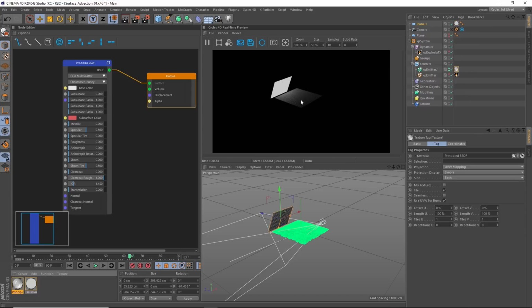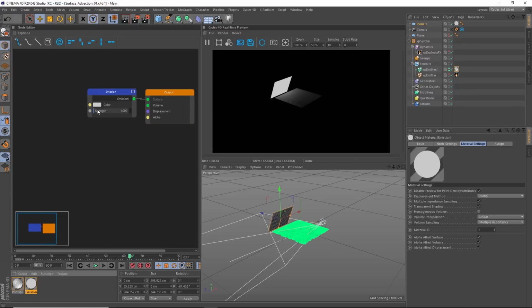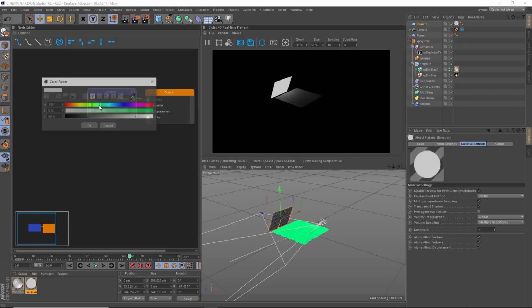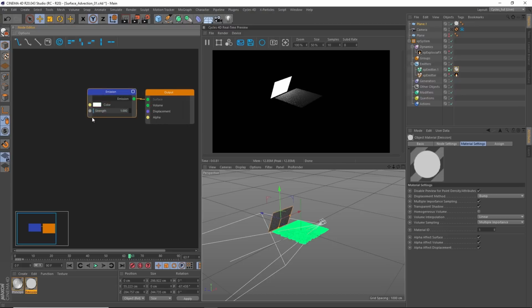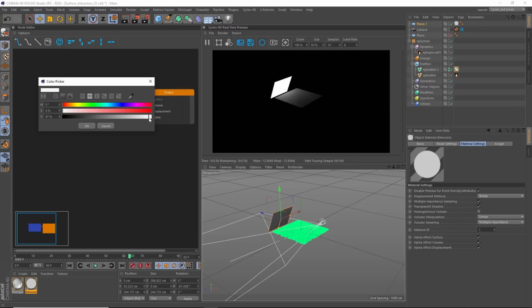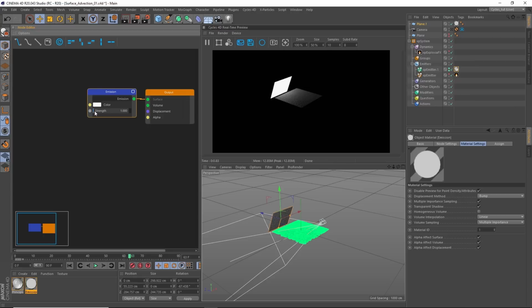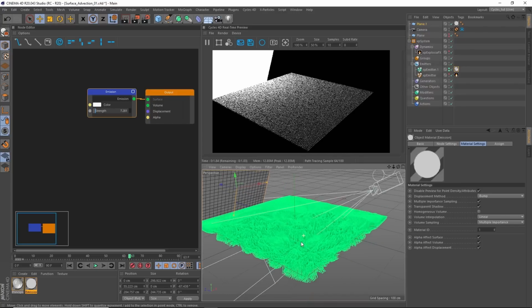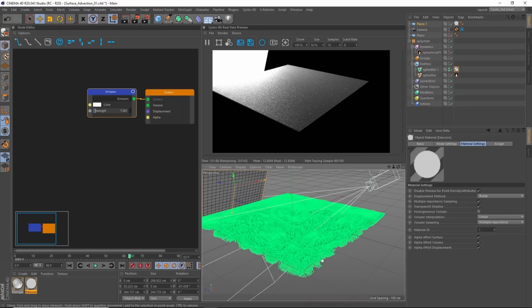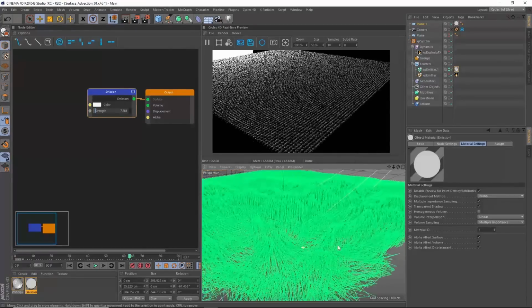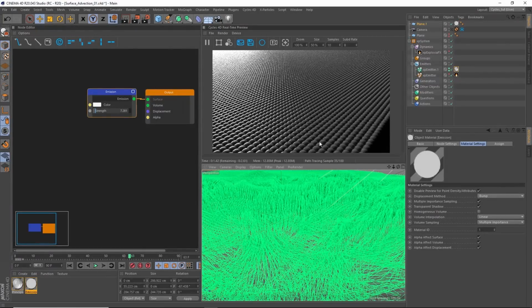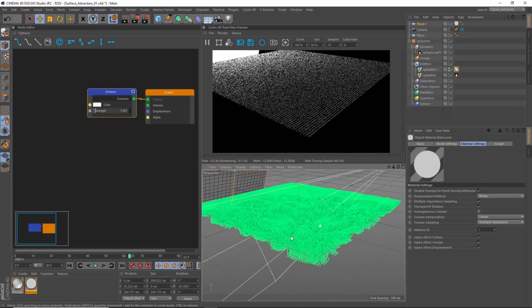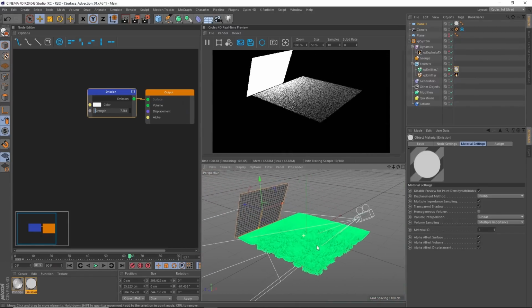And now we can see that we're getting something rendering here. So let's just get that light, and we'll change the color to full white. Actually, let's just slightly off white. And increase the strength a little bit. So now, if I dolly in here, we're seeing something being rendered. And what is being rendered is every single particle. We're not getting the arrows. Every single particle, Cycles is instancing a sphere on those particles. So that's what we're seeing. That's not quite what we want.